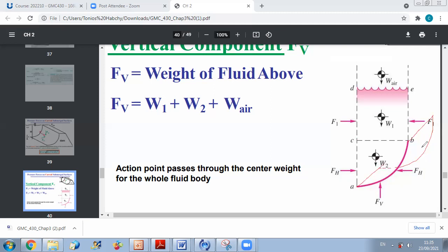Okay, imagine that you project your curved surface on the vertical plane. What will you obtain? You can try to project point by point. The projection of B will give you point C. If I take a point in between, the projection of this point will give you this one, and so on. So you can deduce that the projection of the curved part BA on the vertical plane is CA. And if you do this for all points of your curved surface, since you have constant depth, if you project all depth points, you will end up with this.